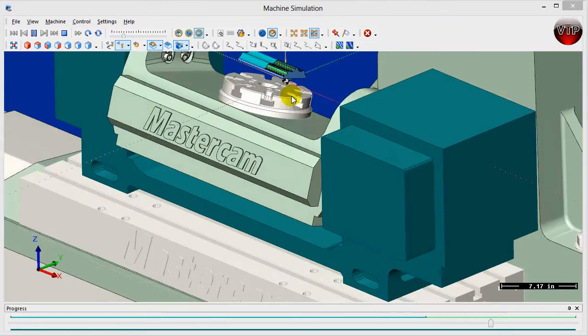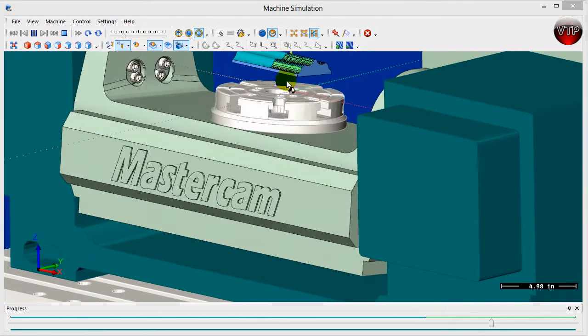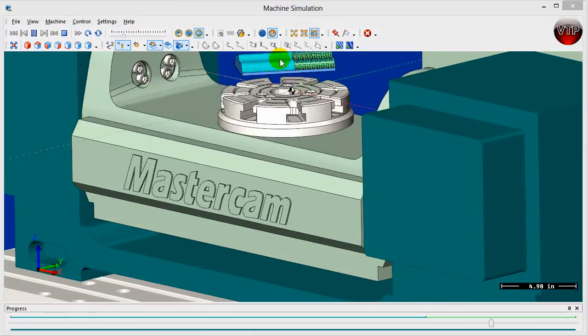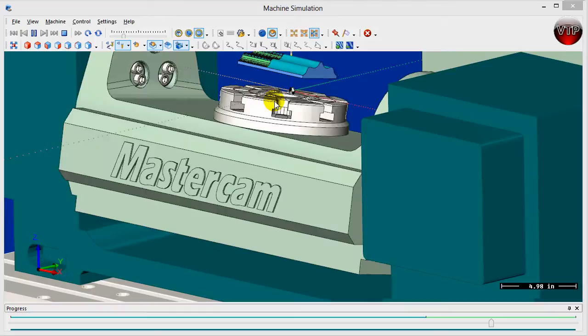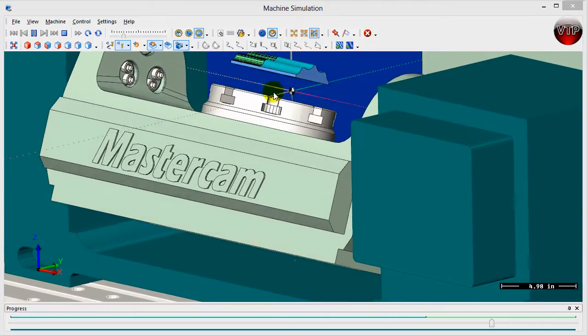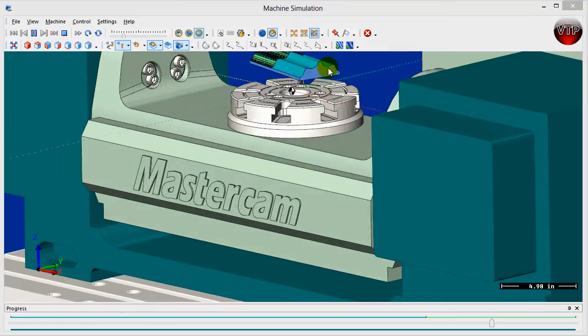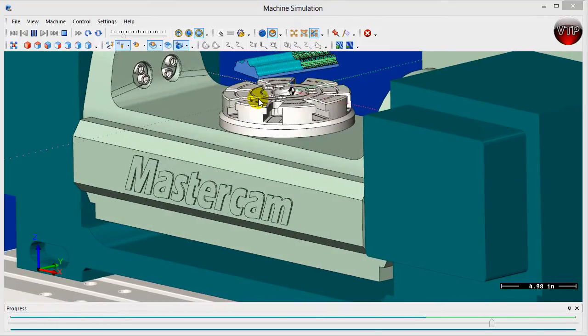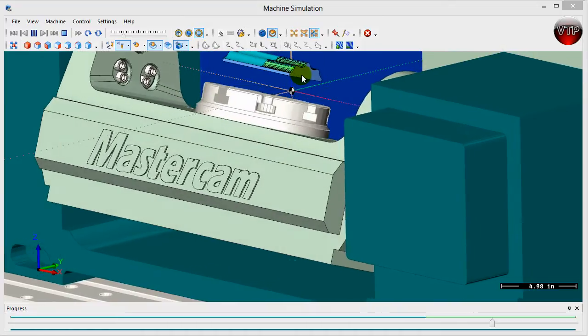This part right here is 2 inches above my stock. So you can see that's why I moved it up, just in case my tool was going to pass this and hit my stock. And it actually was hitting my stock. That's why I went back and changed it to 2 inches above my part. Now you definitely don't want that. If you want to do something like that, make sure that your block comes down and hits this part and it's extended on both sides of the part, so you can have some way of clamping this part while it's machining the surface.